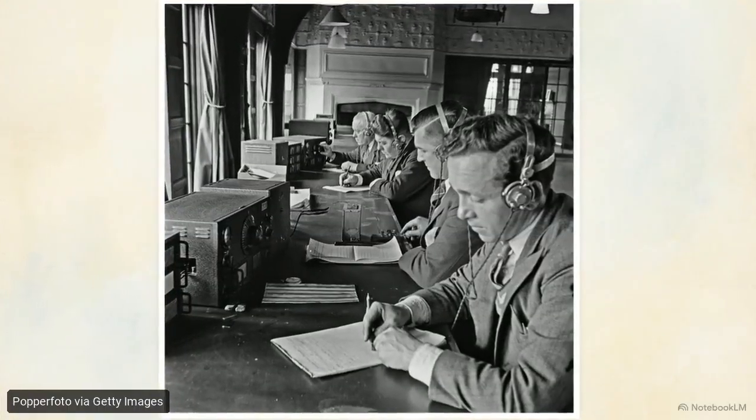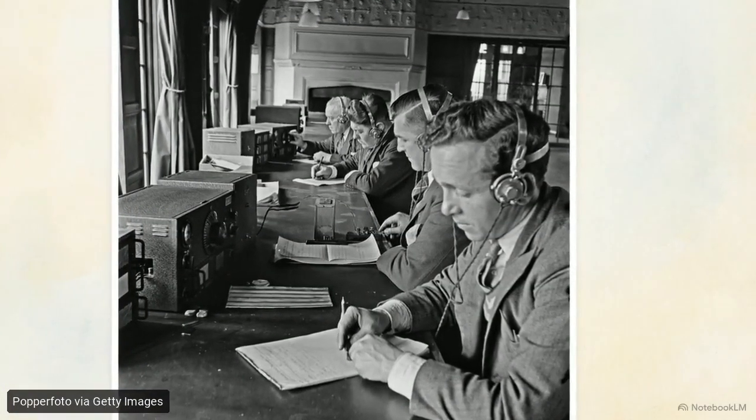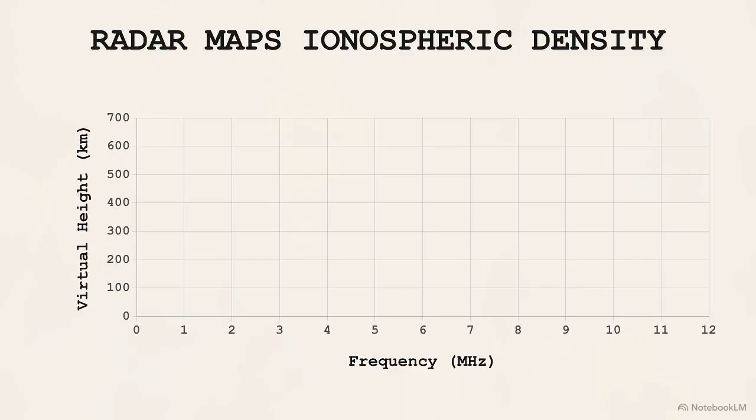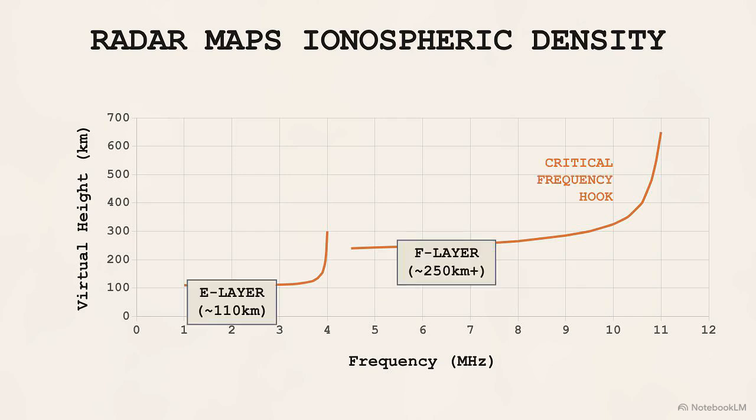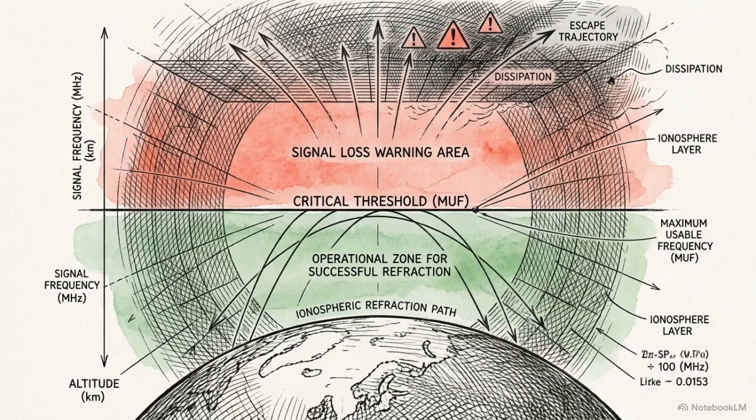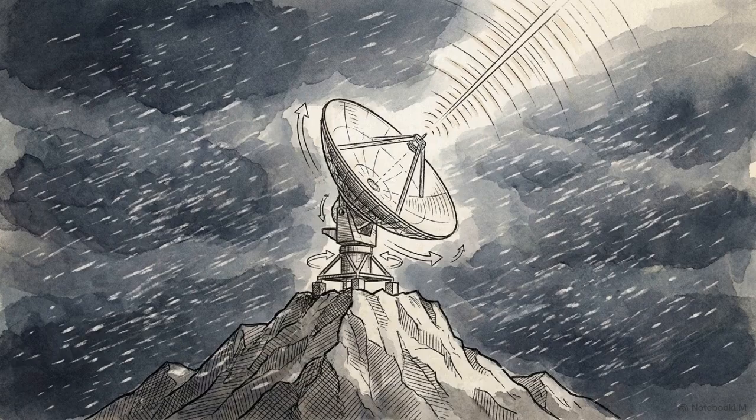Maintaining reliable circuits through these constant environmental shifts requires more than theoretical modeling. Engineers utilize the Ionosonde, a sweep-frequency radar that fires radio pulses straight up into the atmosphere. By timing the return of these echoes across a range of frequencies, the Ionosonde identifies the exact height and density of each ionospheric layer in real time. This data allows operators to determine the maximum usable frequency, the upper limit a signal reaches before it fails to refract and escapes into space. Physics-based models provide the theoretical foundation, but maintaining a circuit requires the continuous empirical measurement of the local atmosphere.